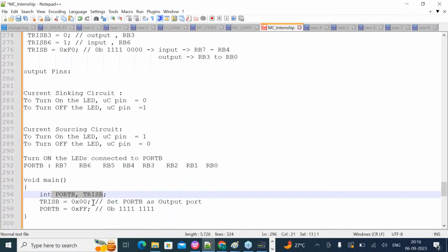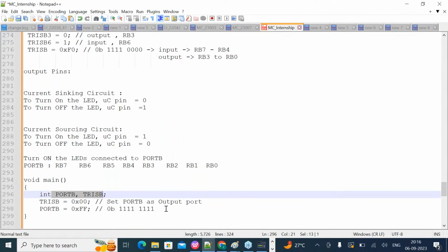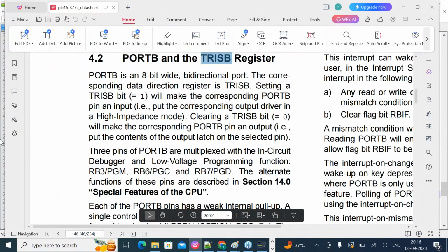So these variables are the registers of our microcontroller. These variables are whatever registers this microcontroller is having. No. So these are just integer variables. So people, what do we have to do? Now we have to open the datasheet and check what is the address of the particular ports, and then we will be writing to that address.